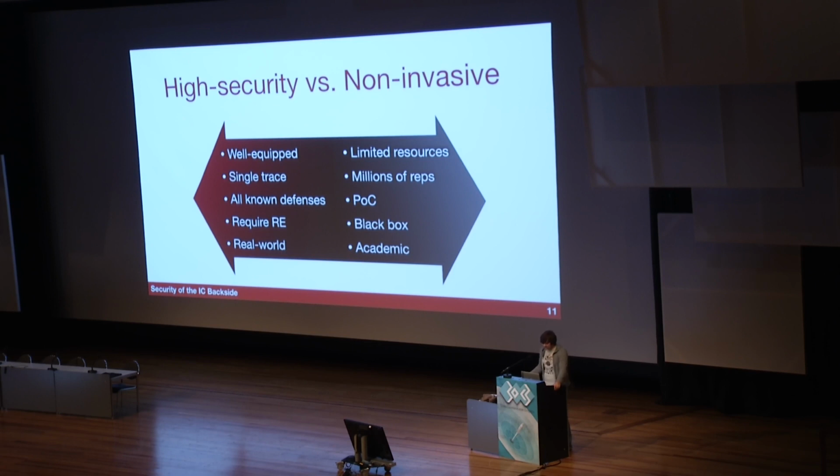That's kind of misrepresented in academia. And like I said before, you want to have a foolproof attack, something you can do with a single trace. For side channel analysis, a lot of times you'll talk about millions of traces. So what do people do to prevent side channel analysis? They have a counter, and the counter usually counts to 2 to the 16 minus 1. So it counts to 65,000, and then after that, the card erases itself and you're done. You can't do anything on this card. So you can't talk about doing a million repetitions to extract some sort of key.